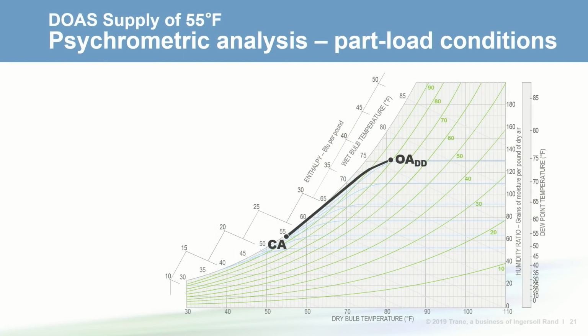Now before we go any further, the zone level analysis required several iterations, but I'm not going to show those. Instead, we're going to just show the final closed loop for brevity. Return air enters the terminal unit and is cooled down, but not as cold as cooling design due to the reduced space load. The conditioned outdoor air and terminal supply air mix. Finally, the conditioned return outdoor air mixture heats along the SHR until reaching the space dry bulb temperature.